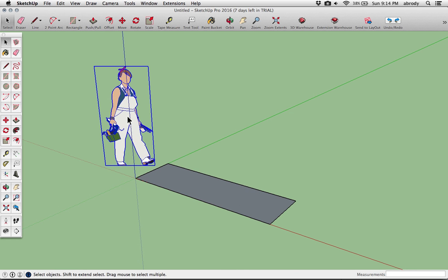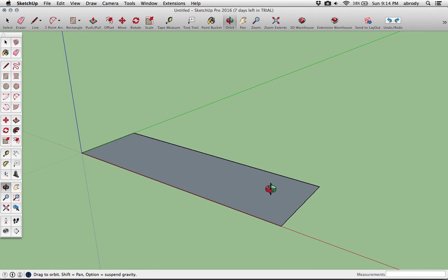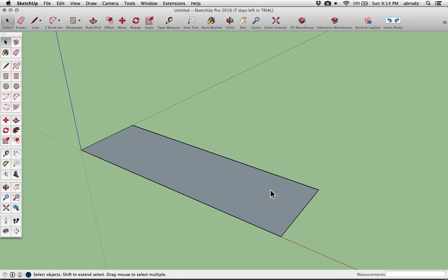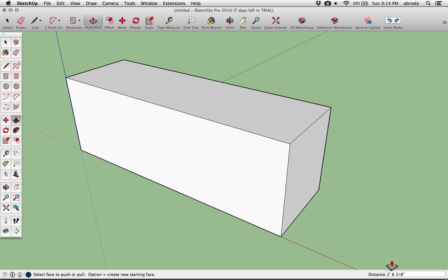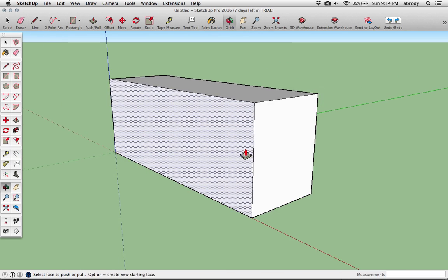When you're drawing this object, I think I'm just going to get rid of this lady here. Now I can't change the dimension, right, without moving objects, of course, moving lines or something like that. I think I'm going to use my push-pull command. I just hit P to get it to activate. And again, as you can see, it types the dimensions in, and I can either click and drag until I get the dimension I like, or I can type in some number. I think I'll just type in 36. It seems to be a very nice height for a table.